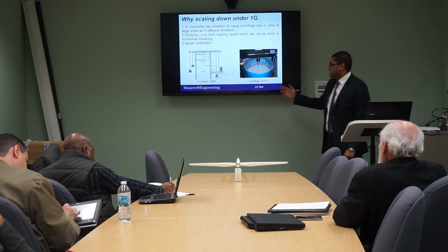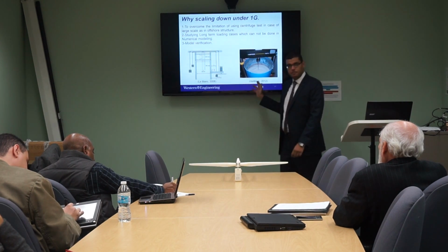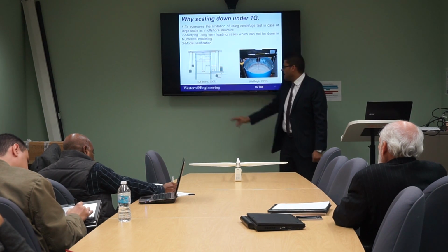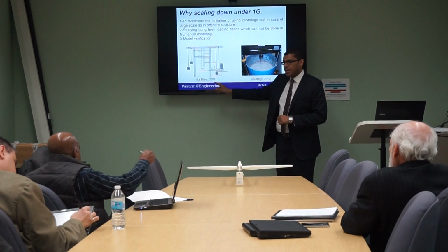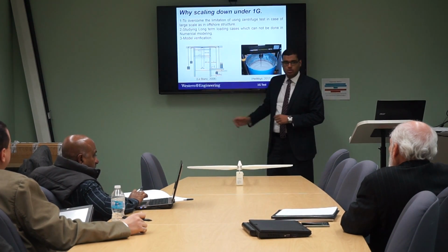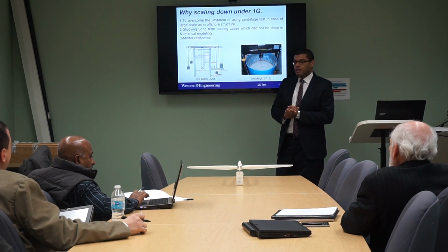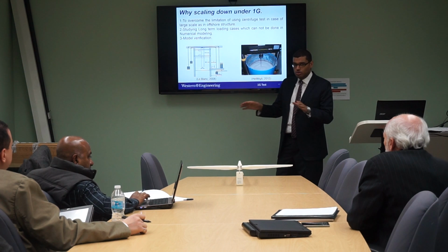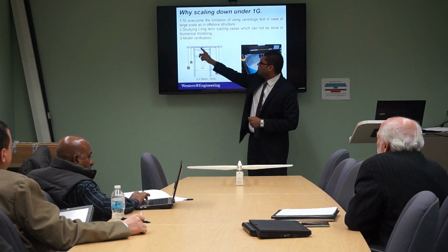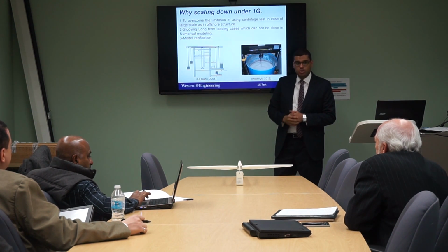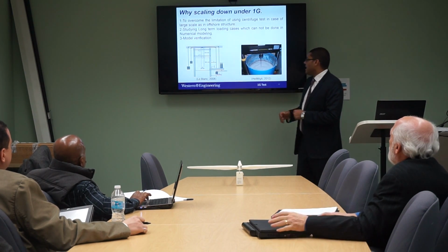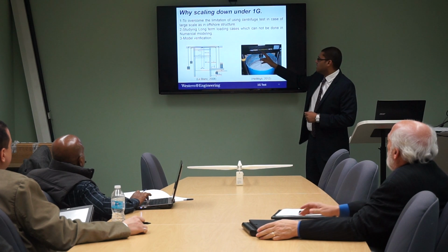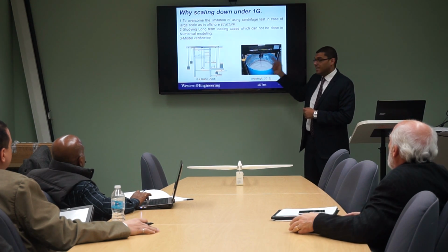In our test we depended on two major works, LeBlanc 2008 and Hull-Magic 2012. In LeBlanc 2008, he also used a monopile to resist load from a wind turbine, but he used typical loads. He used the wire pulley technique for static load and a motor from AC for cyclic loading. For Hull-Magic, he used an Instron device to apply cyclic loading on his pile.